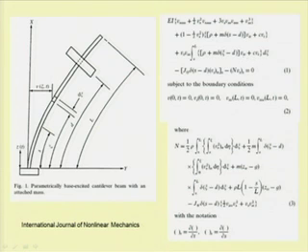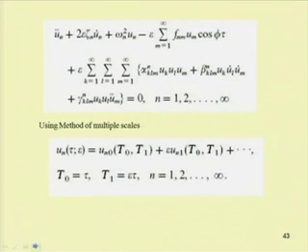So, in this equation, this is a nonlinear equation. In this nonlinear equation, m is the tip mass, rho is the mass per unit length of the beam, and here this Dirac delta function is used to show the position of this tip mass at an arbitrary position. So, by using this governing equation, one can use this Galerkin procedure to reduce